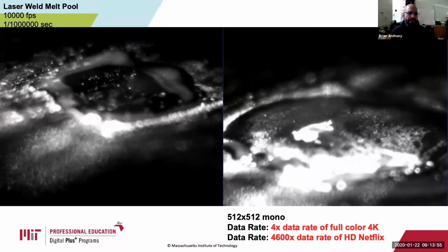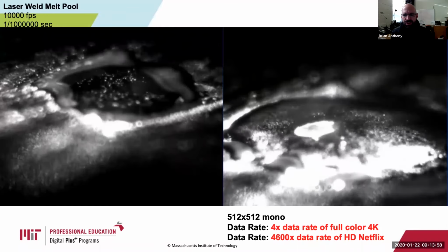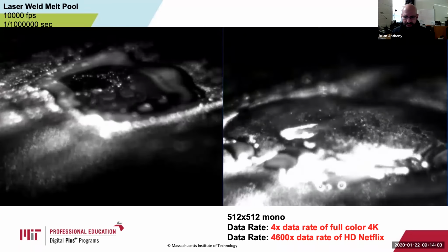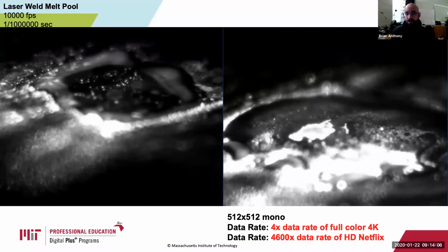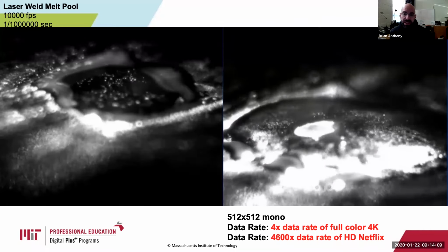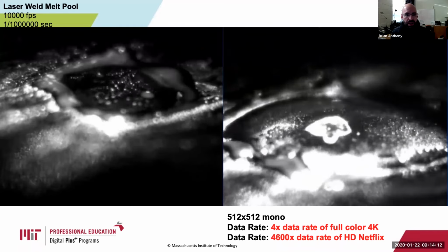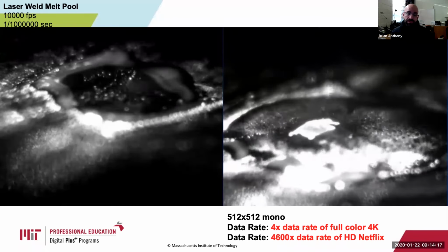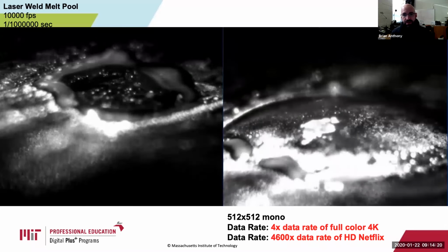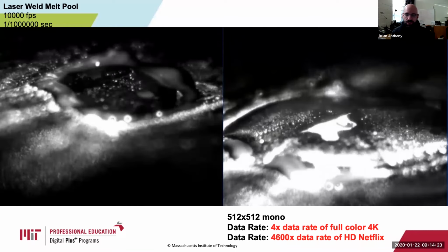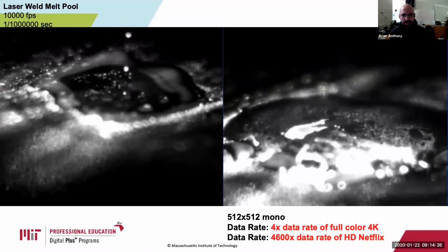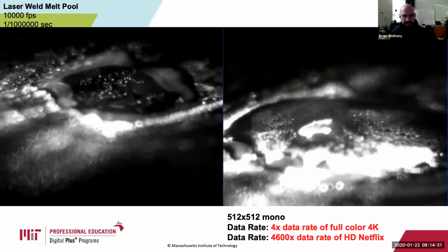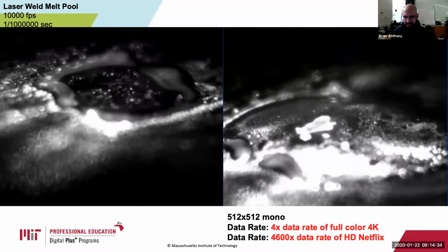but also to convey the breadth of scope and scale with which you can approach manufacturing. This is a high-speed video recorded at 10,000 frames per second of a laser weld melt pool. And this is a process that you can't imagine putting any sensor on directly. The camera is certainly a sensor. Later in the class, one of the modules that you'll study is how to use high-speed video to extract information that is relevant for process control. Otherwise, there's no way to easily put a thermocouple or any kind of fluid sensor into this thing that's being heated by lasers and melting.